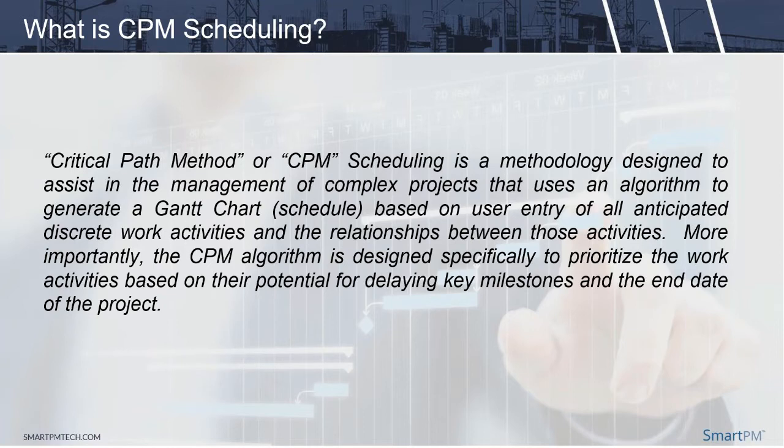So what you get when you use a CPM schedule is a plan. And that plan comes with more than just activities. It's a prioritized list of activities: which are higher risk activities that need to get done as timely as possible, which ones have a little bit of room for delay, and which have a lot of room for delay. So really that's useful. Useful knowing, if you have a complex construction project, that you can look at a schedule, look at a technology, and it will tell you, here's what's going on today, here's what's going on tomorrow, here's what's going on the next couple weeks, and here's the order in which they should be completed. Here are the ones that absolutely need to get completed in time, and here are the ones that have a little bit of room for error.